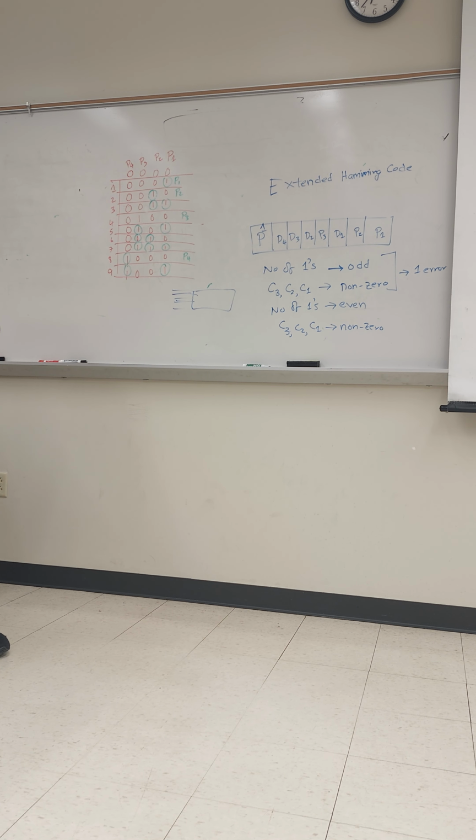On the other hand, the OR gate is doing the summation, A plus B, or B plus A, and the output will be low when both inputs are low. Very common thing. Here also we can add any number of inputs. Then the inverter circuit: whatever you give, if you give 0, it will create 1. This is the inverter. Okay. The NAND gate is just the opposite of the AND gate, right? The output will be low when all the inputs are high. Good. Then for the NOR gate, the output is high when both inputs are low.